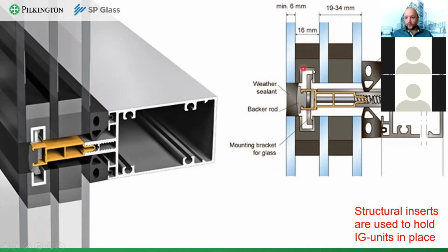A lot of aluminum profile companies have their own designs of the structural insert. So you need to provide full information about which structural insert you use and how they will be positioned, because the total secondary sealant depth is highly dependent on this. Imagine here, in the place of a structural insert, in terms of holding the glass, the sealant depth is like this. So far less than an ordinary one.